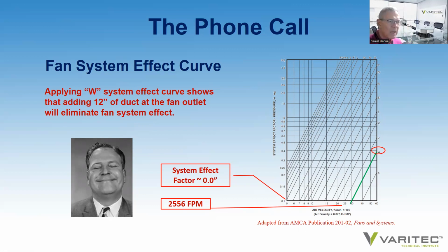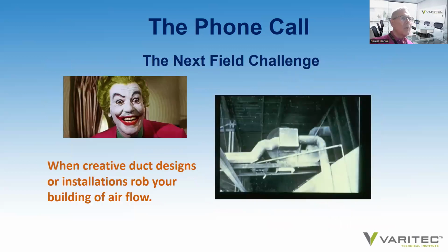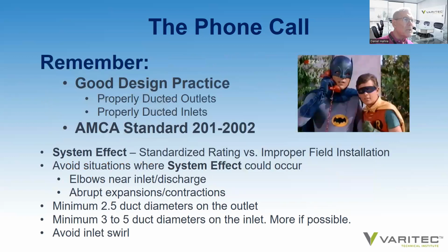In actual designs, any engineer who's joining us, if you're laying out utility vent sets, make sure you have some element of straight duct on the discharge of that fan so you don't have unforeseen static system effect, static pressure additions to your system. So the next time you have a challenge in the field with creative duct designs and creative installations, please remember to use good design practice for your ducts.